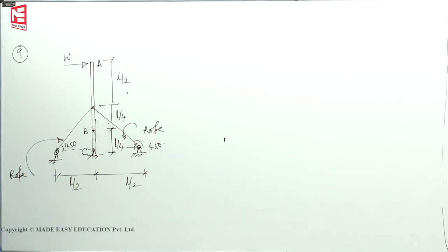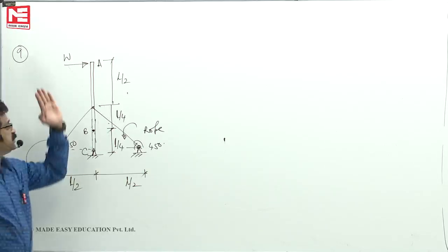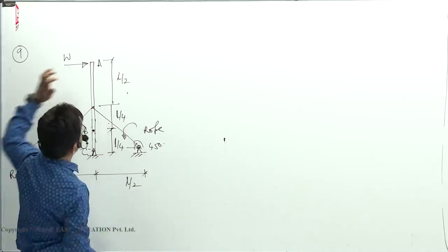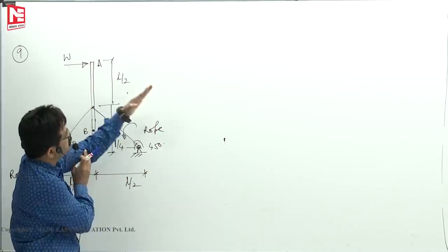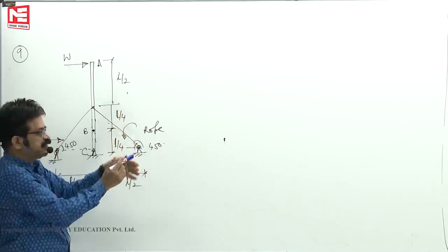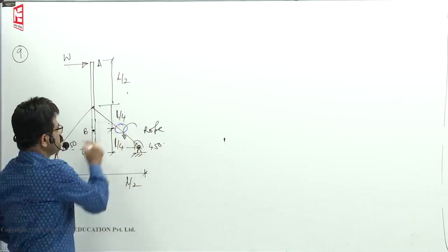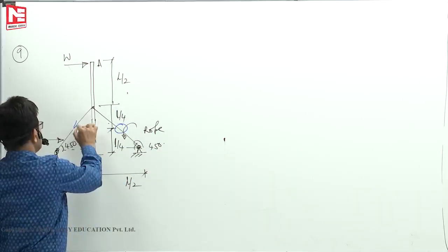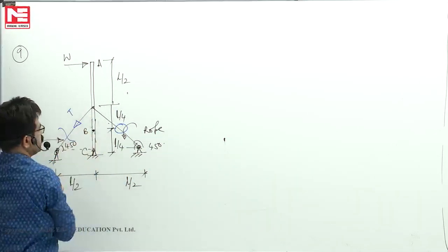See, when you are drawing the free body diagram, see, this is the bar, this is the rope. When I push it like this, assume that it deflects like this. This will be subjected to compression. That means force in this rope is 0. This will be pulled when I am pushing it like this. Let us call first this as tension T after cutting them.